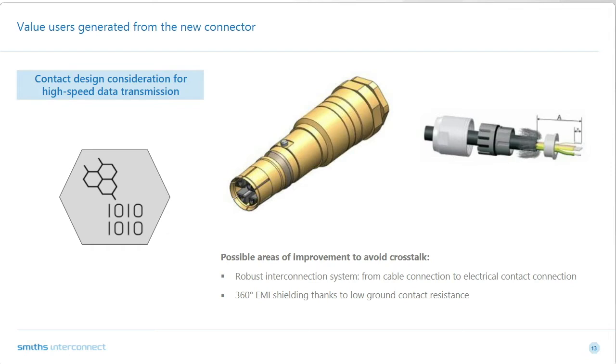Now, EMI is another key aspect when we are looking into this. One has to make sure that their system is compatible with the communication system, for example, in case of rail, the signaling system. EMI is strongly related to earthing methods because the current passing through the earth connections can be directed by high-frequency harmonics and produce high-frequency electromagnetic fields.